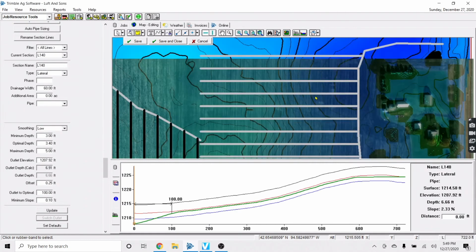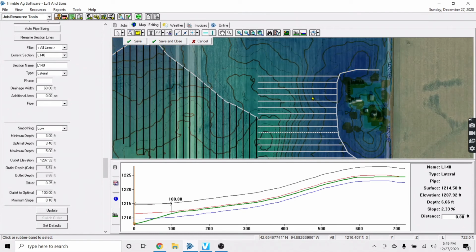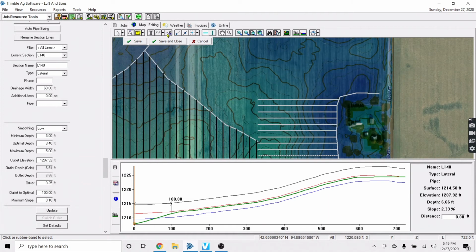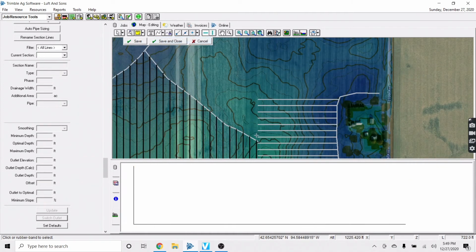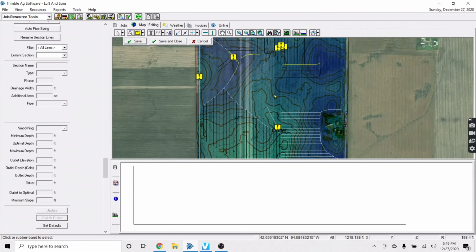We're going to create offset on that one. And it's probably going to be at least 15 to the right. Let's go back in there a ways. So then those could start getting long again, actually. So we need to put a false contour in up here on this hill. Probably right along here. Now see, we're getting into a section here now. There's another contour here. These lines will work if we keep extending them here, but this is where we need